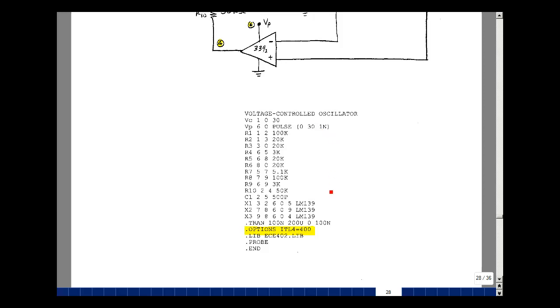Now when doing simulations with a lot of parts in it, like this, I've got 3 of my macro models. If I had the full chip simulation, it's not clear I'd even get convergence. But one of the things you're going to run into when you're doing a lot of parts is that sometimes you'll be iterating an answer and all of a sudden the program will just quit. It says it can't find the answer. And it really has to do with one of the artifacts of the original program. To save time and to save money in the 1970s, the program stopped itself from running too long. Whenever you're iterating at a point in Spice, it tries up to 10 times, and if it can't find an answer, it just quits.